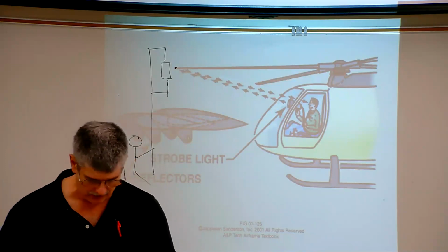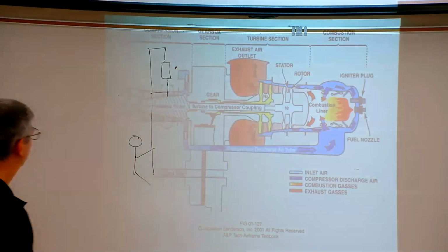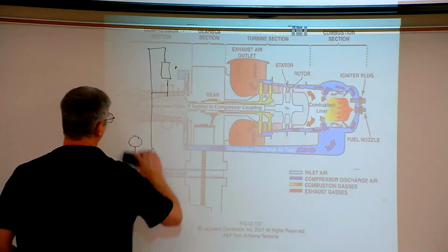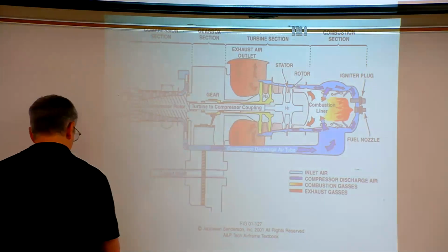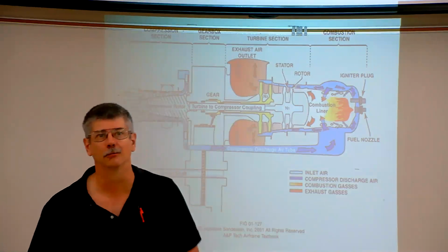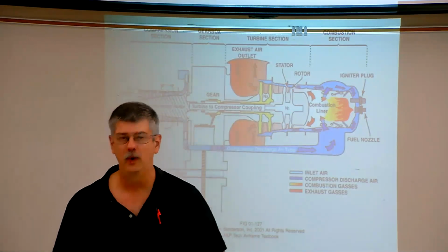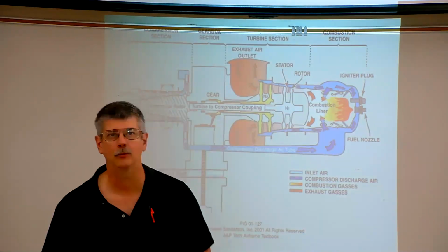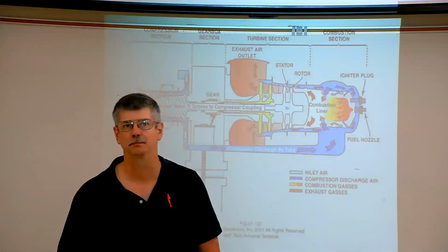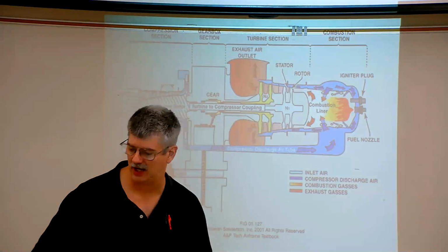So that's that. That's helicopter power systems. Yes, helicopters can use reciprocating engines, but keep in mind, reciprocating engines are generally heavy for the amount of horsepower that they can put out. The helicopter really came into its own when the turbine engine was developed. With that, we have a lightweight, very powerful engine that likes to run at a very constant speed. And so turbine engines do a fantastic job.